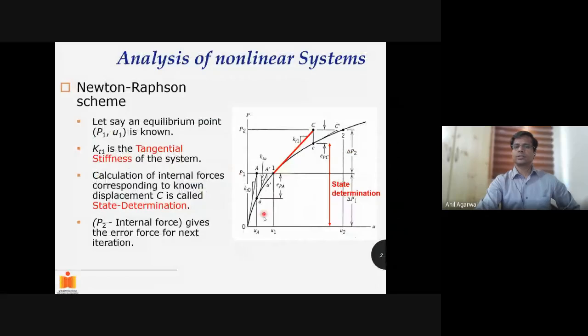Another thing that you have to do is, after calculating the stiffness, you divide the force with the stiffness. That is the same as your stiffness method, because you are already doing that. When you were saying A is equal to S multiplied by D, force was equal to stiffness multiplied by displacement, in order to solve for the displacement, you were dividing A by S. A divided by S was the displacement that you were calculating before. You also need to do that. So that is the same step as before.